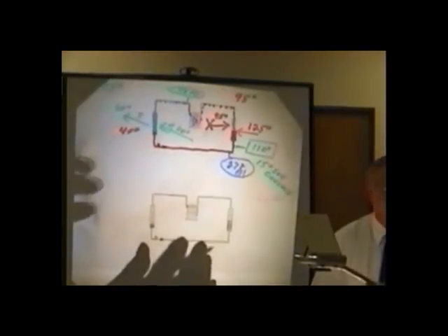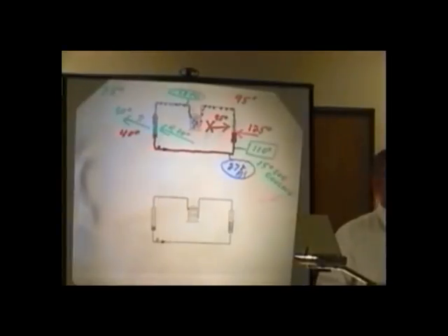And boy, do you have to know this to diagnose. But you see how easy it is to take. We're telling you, you can diagnose in 15 minutes. Let it run for a few minutes and take your subcooling. Measure your pressure. That's easy. Convert it. Stick a thermometer under. Let it run for a few minutes. Take a temperature reading. Subtract. Now you know your subcooling.